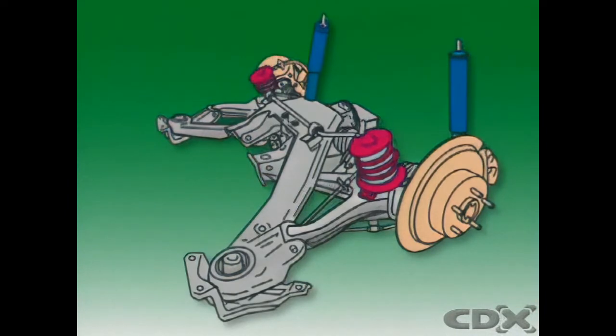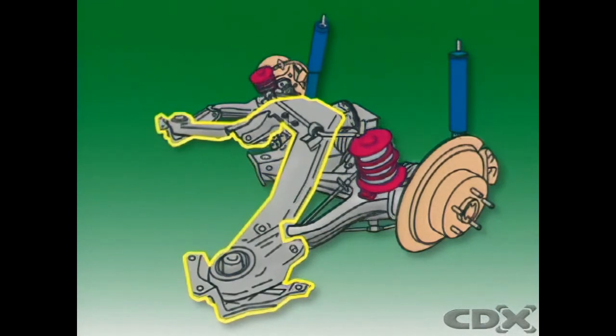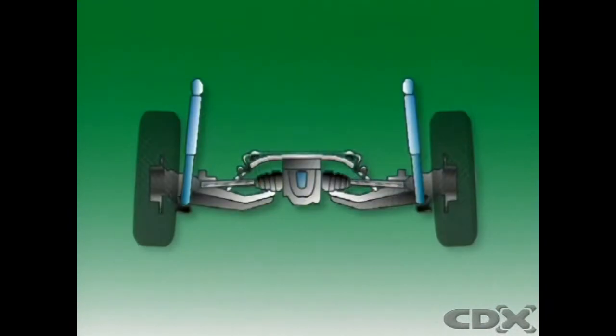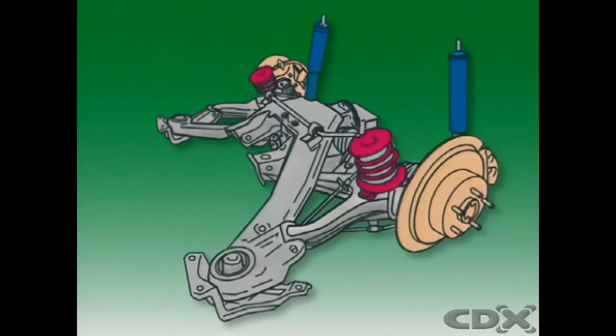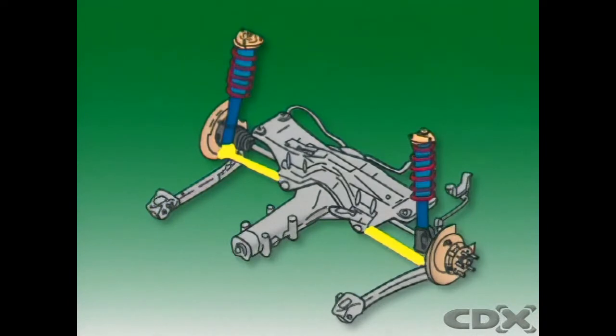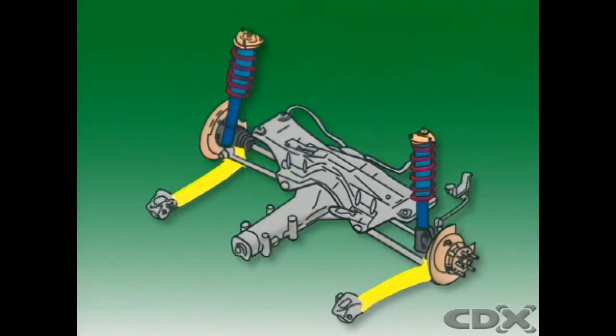On rear-wheel drive vehicles with independent suspension, the final drive unit is fixed to the vehicle frame. Drive is transmitted to each wheel by external drive shafts. Suspension is normally by coil springs, and each wheel unit is located by semi-trailing arms or by a combination of lateral and longitudinal control arms to the frame.